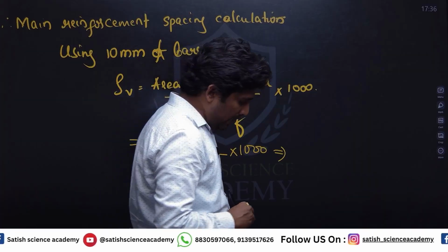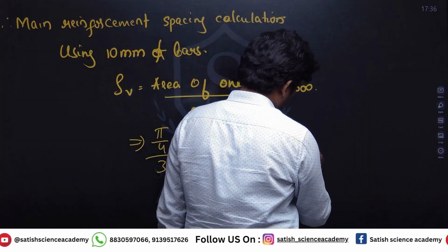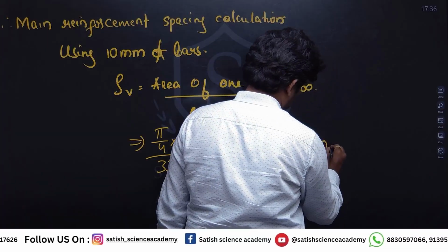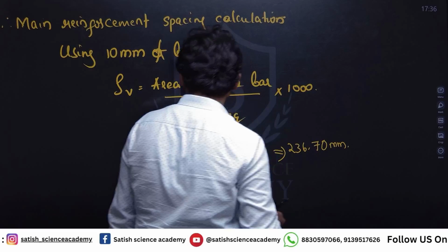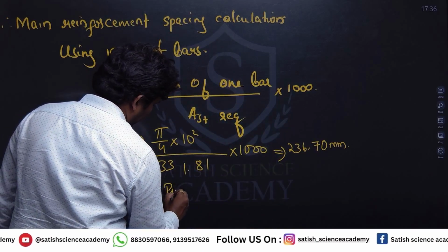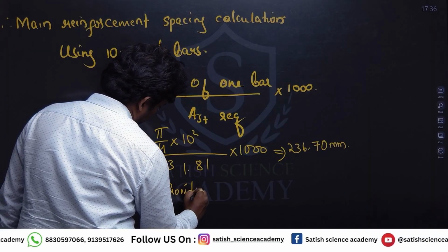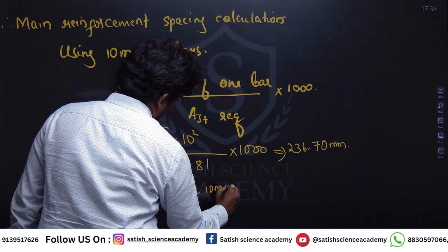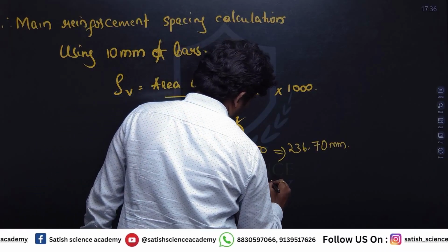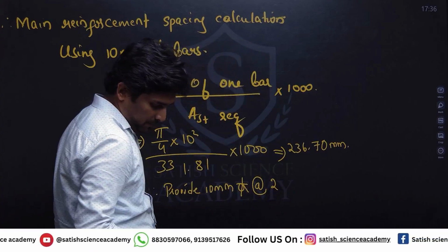So this is 236.70 mm. Therefore, provide 10 mm dia at 200 mm center to center.